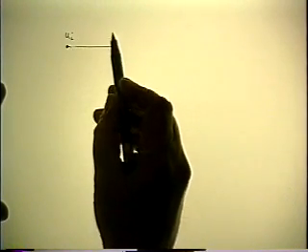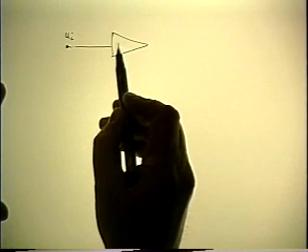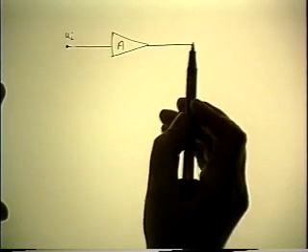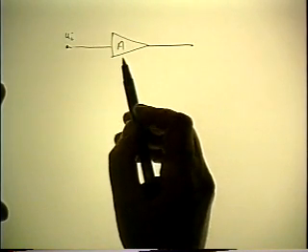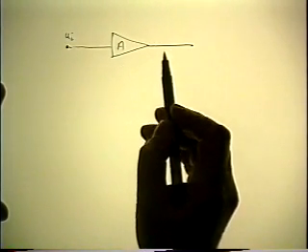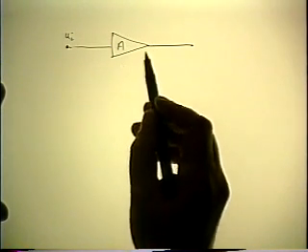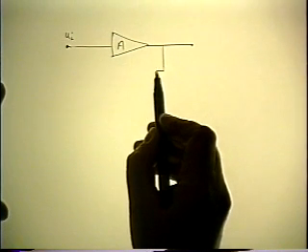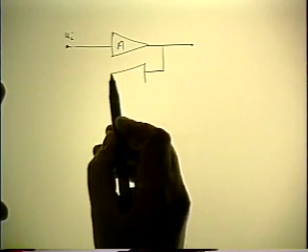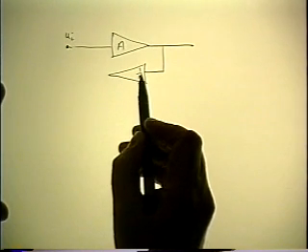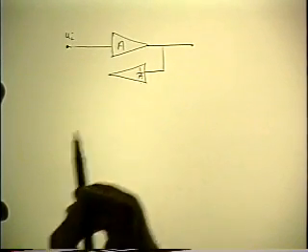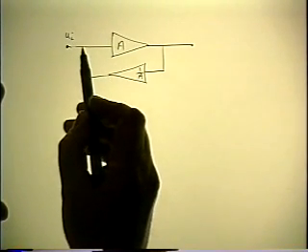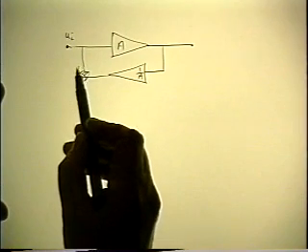We want to amplify it. So we go through an amplifier with a gain of A made out of lousy vacuum tubes. And what comes out is an amplified fundamental plus harmonics coming from the nonlinearity or the distortion. So he says, let's take that output and we'll attenuate the output by the same factor that we just amplified it, 1 over A. Then let's subtract that from the original input.